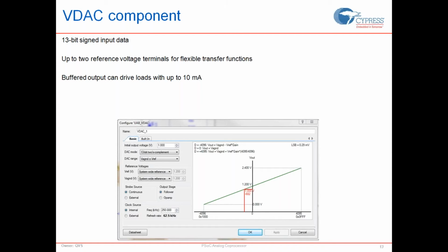The reason you would use a strobed VDAC is that the data entry into the VDAC is something you want to control, meaning the write into the VDAC might not be happening at regular intervals of time because of firmware delays or DMA latency or something. So you don't want your VDAC to refresh at a different point in time,